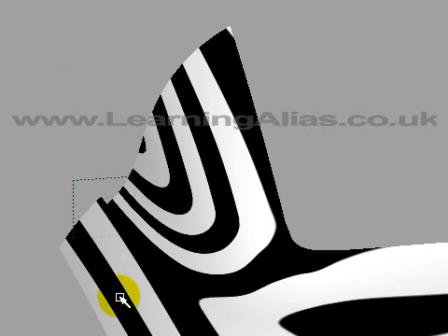Let's take a quick look at the model with the zebra stripes on, and the whole point really of this C-pillar that my students are modeling at the moment is to get this beautiful G3 curvature continuity here. You can see it there, and you can see it around there.